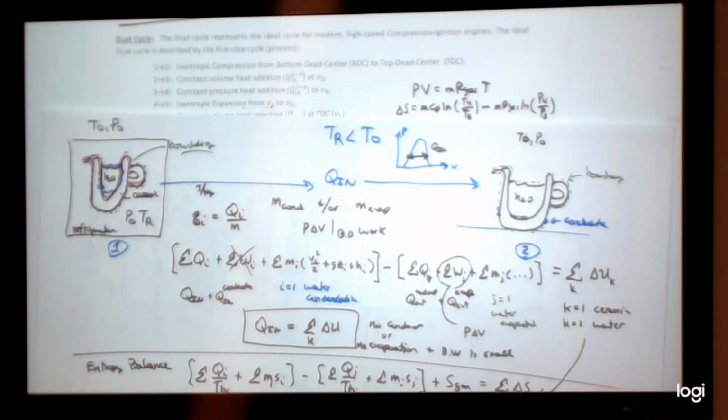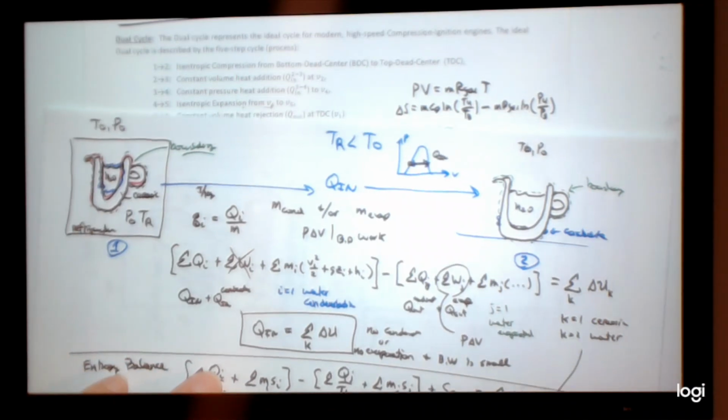And then small q also means like specific heat or... Yeah, that's why I don't want to say specific, because usually it's written like that, and that's why I don't use the small q in any of my lectures, even though the book does it, because then I would be saying it's kind of a specific heat, which it isn't, because specific heat has to do with the change in temperature, and this q can be, in this case, what was that q related to? Phase change and sensible. Whereas Cp, right, the Cp part is usually sensible. So I don't use a small q. Yeah. But I'm glad you asked the question. That's why. They get rid of mass in all the equations.